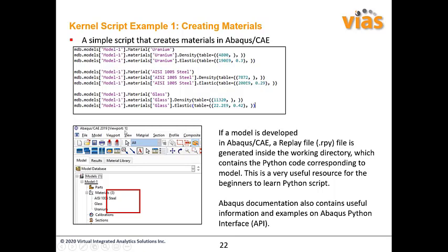Using very simple code, I can always automate the creation of the materials. Of course, I can create the materials manually, but suppose I'm going to be producing 10 or 20 different models in which the same materials are going to be used. Then it's very efficient for me to create this code once, call this code up here, run it, and it will generate the materials for you in a fraction of a second.